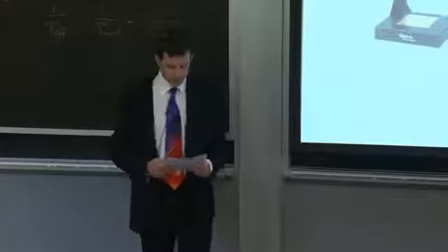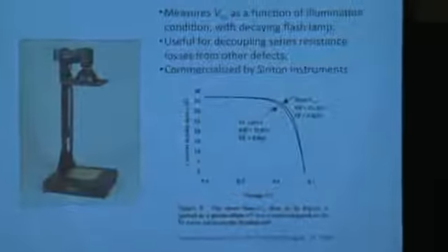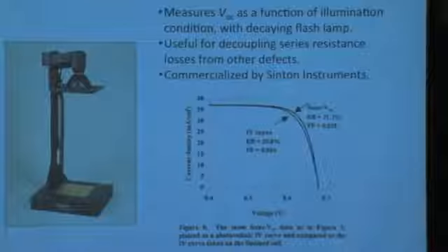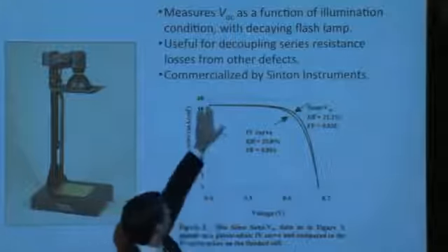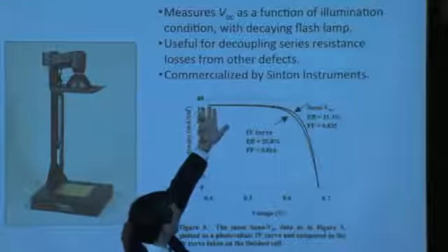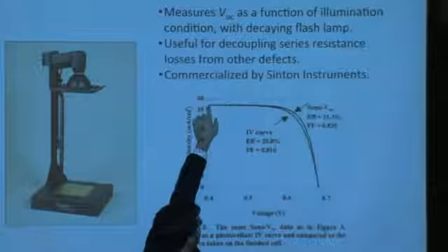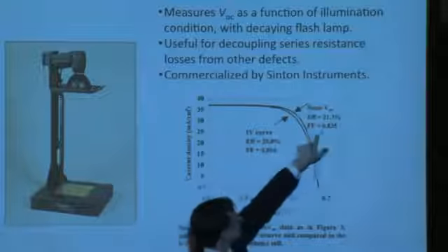OK, so we can derive an IV characteristic by translating that open circuit voltage into an implied bias voltage. And knowing the short circuit current density up front, essentially by measuring the solar cell device in a solar simulator, we can obtain the short circuit current density. We pin both curves up here at the measured short circuit current density, and then we plot both curves out, the IV curve and the sun's VOC curve.